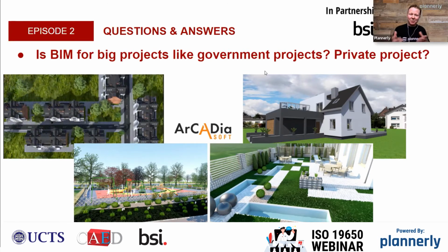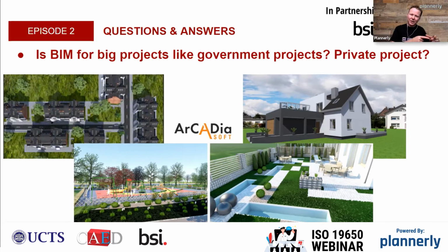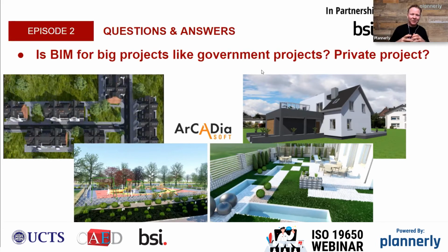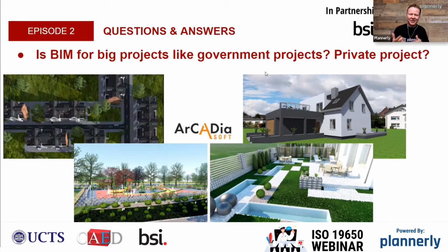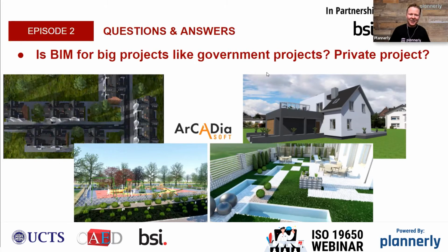And what we found with BIM was that the opening wasn't aligned in a way that they could actually access without a lot of safety concern of having to swing somebody around to be able to get onto the first rungs of these ladders. And as a result, they would have had to recast the slab, and they would have only recognized this when they were placing it in that location. So we actually saved a huge mess just by turning these few 3D concrete boxes into BIM objects and understanding it. So you can save even on the smallest projects.